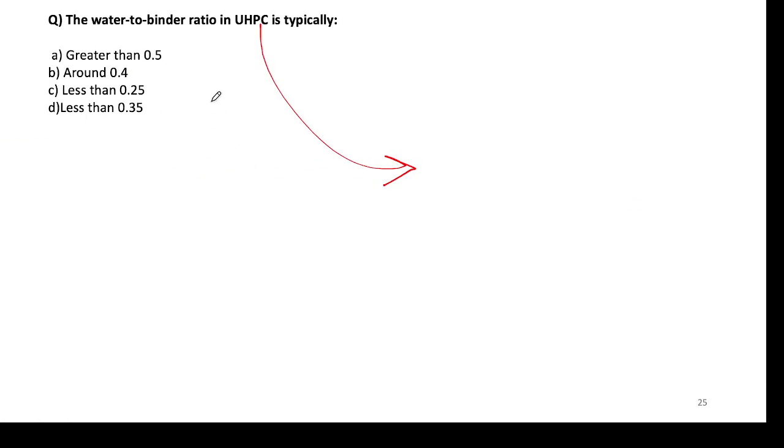Okay, let's see. To achieve the ultra high performance strength of the concrete, we require a very low water to cement ratio, even less than 0.25, and achieving the workability required for placing the concrete is also important. Hence the use of superplasticizer is very essential in this condition, and we have to use SP in a very high amount to provide fluidity to the mix. The lower the water to cement ratio, the higher the strength and the denser the microstructure.